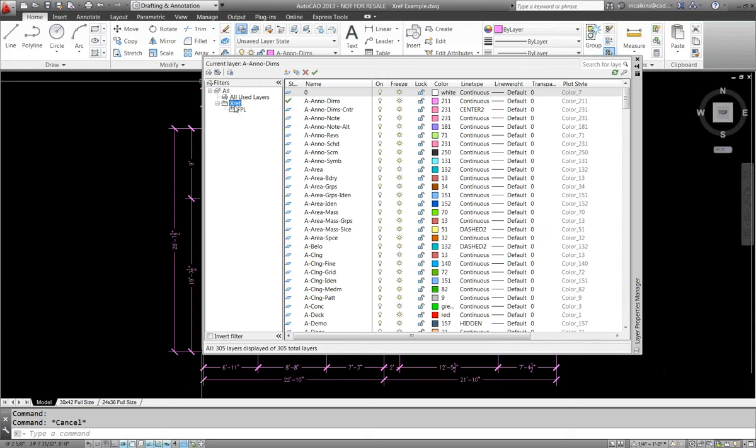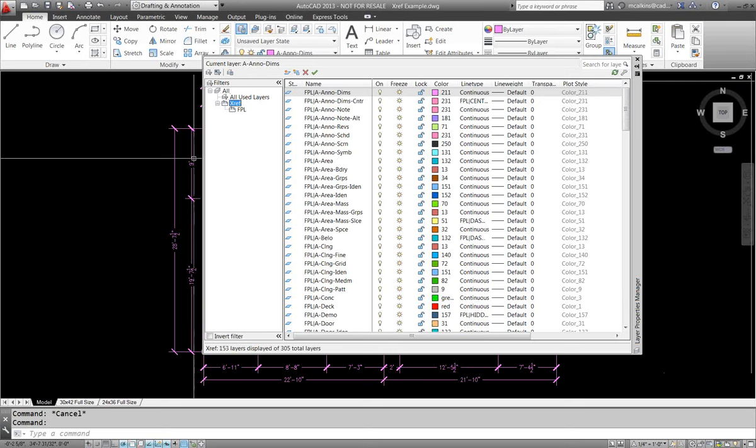These show up instantaneously when you place an XREF in. And you will get a list of all the XREFs here. You can individually select the XREFs and you'll see a list of the layers being pulled through with the XREF. You can click the XREF heading and it will actually display all the XREF dependent layers. So if you have multiple XREFs, they would all display in here.